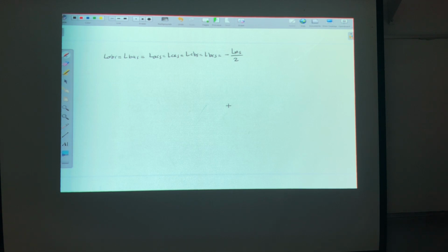Okay. So if I'm having 5 phases, the angle between the axes will be what? 360 over 5, which is 72. So in this case, I need to project by cosine of 72. If I have 9 phases, it will be 360 over 9, correct? So this angle is decided by the number of phases, by symmetry, I mean the phases are symmetric. And in this course, I'm discussing only a symmetric machine.